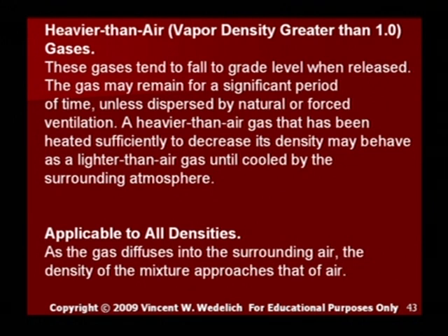And obviously the point here is, if you are dealing with a gas that has a vapor density greater than 1.0, then you need to know that if I have below grade areas such as ditches, those ditches are now classified as Div 1. And then the areas above that, 3 feet above that, would be Div 2 areas.